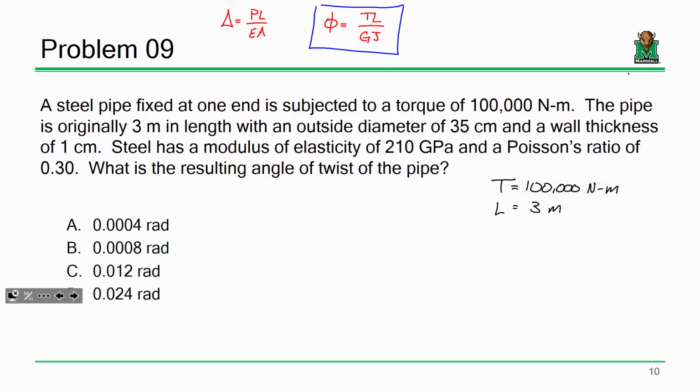If I take a member and I apply some stress, it deforms, right? The relationship between how much it deforms and how much stress I apply is Young's modulus. Now Young's modulus is for pulling things this way. G is the shear modulus for if you shear it. Now how do we calculate that?